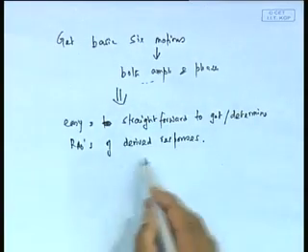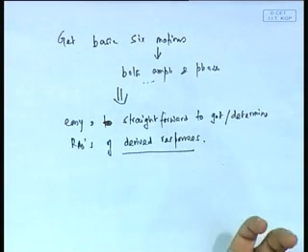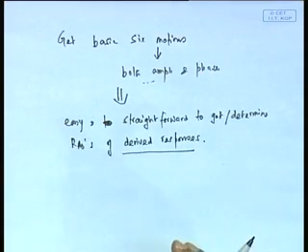These derived responses are nothing but combinations of this. That is the point I am trying to insist upon. As far as practicality is concerned, you can always open up a book and find the exact relationship, but the point is that it becomes fairly trivial to obtain. If I have these 6 modes of RAOs and the phases, I can quickly, by just one line, find out the RAO for a particular motion, say ZB, vertical velocity or relative vertical velocity or whatever I want. From there I can find out whatever I want to know again by just one line.